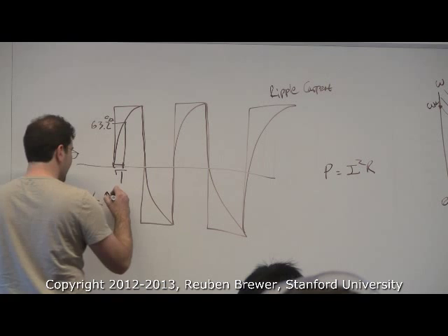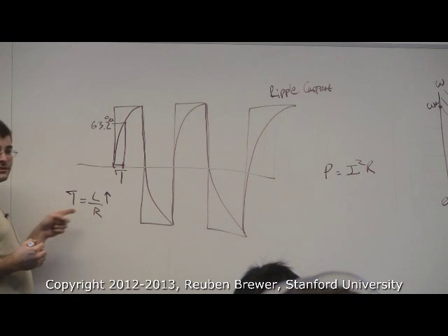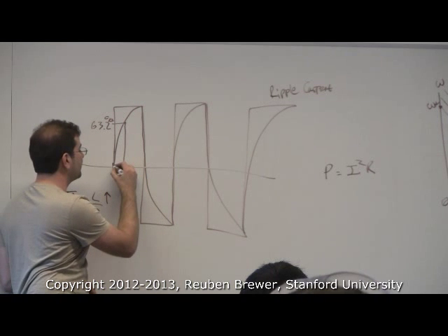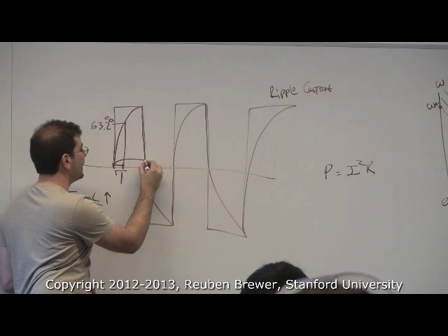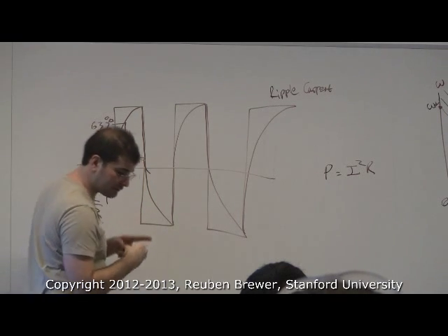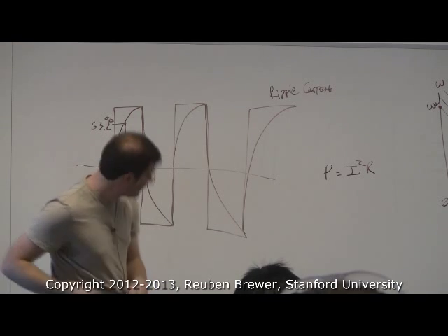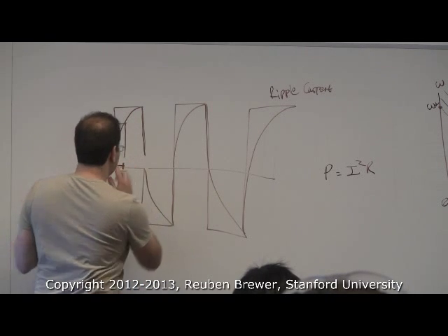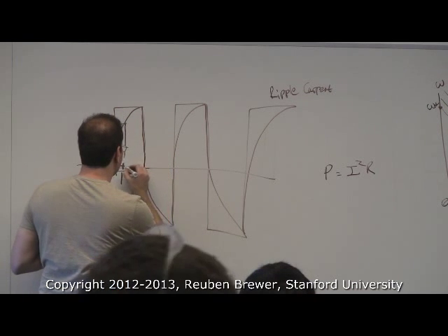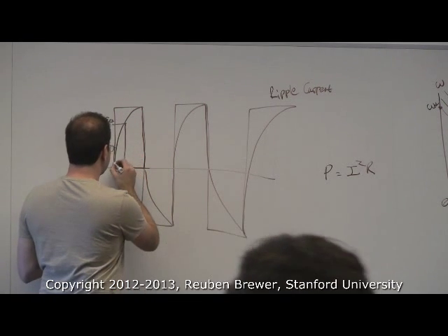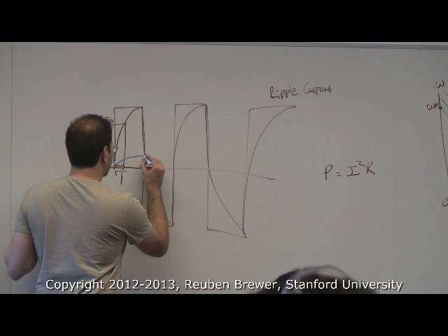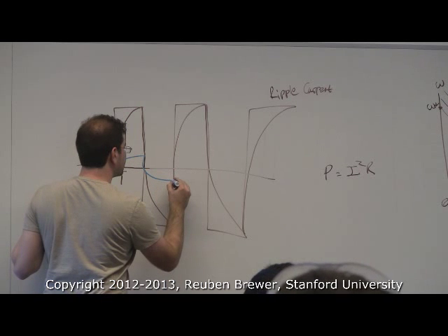So let's increase L. If we increase L, the time constant gets bigger, and for this same PWM frequency, we're only going to get part of the way developed. Let me draw that in a different color. Can the time constant be bigger than the period of the wave? Bigger than the period, yeah. How easy is it to go into a motor and change the inductance? Beautifully simple.